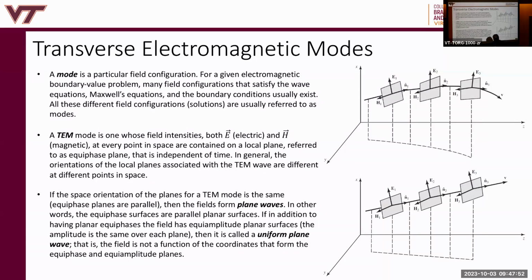The reason why we like plane waves is because if you're far away from an antenna, where we normally care about the radiation pattern, which is called the far field, we're far enough away that the radiation from it to us looks like what's called a local plane wave.